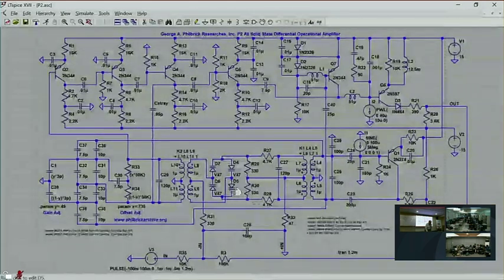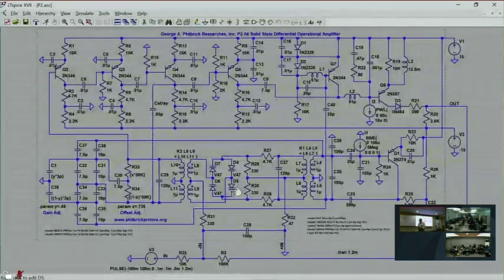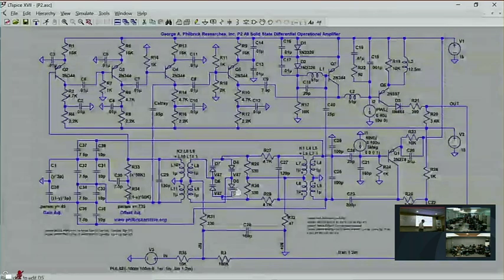Also, it required very little current, very low bias current. It doesn't take much current to imbalance a varactor ring, especially when that imbalanced signal is being driven back to zero with the full open loop gain of an op amp. So the bias current was exceedingly low, typically 10 picoamps.